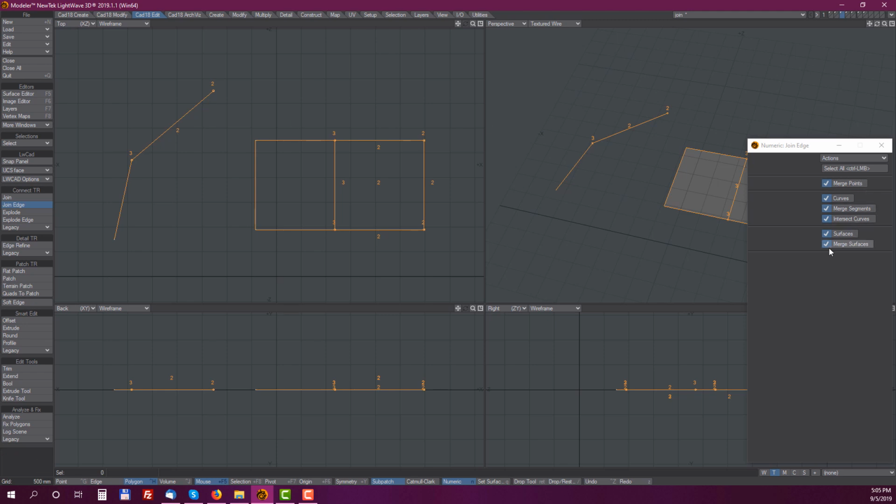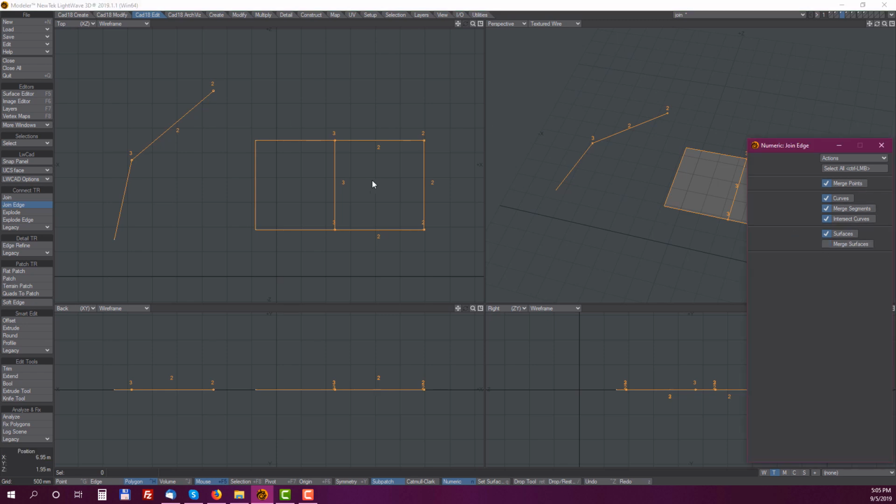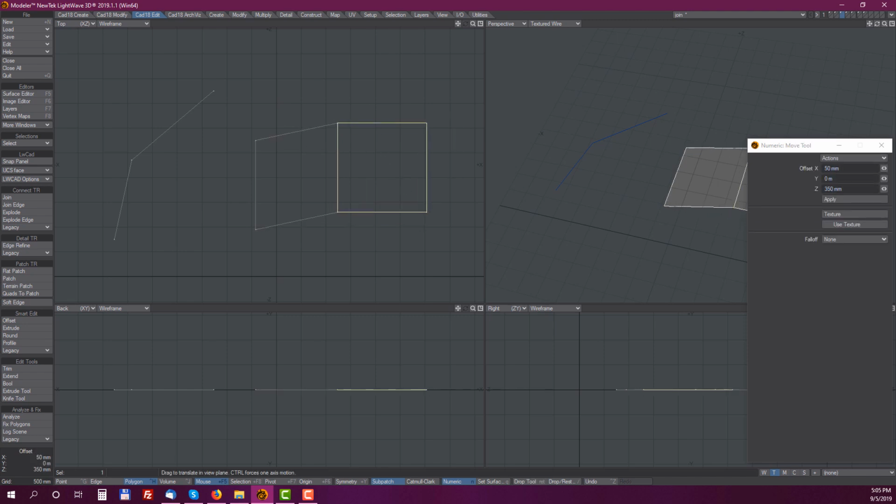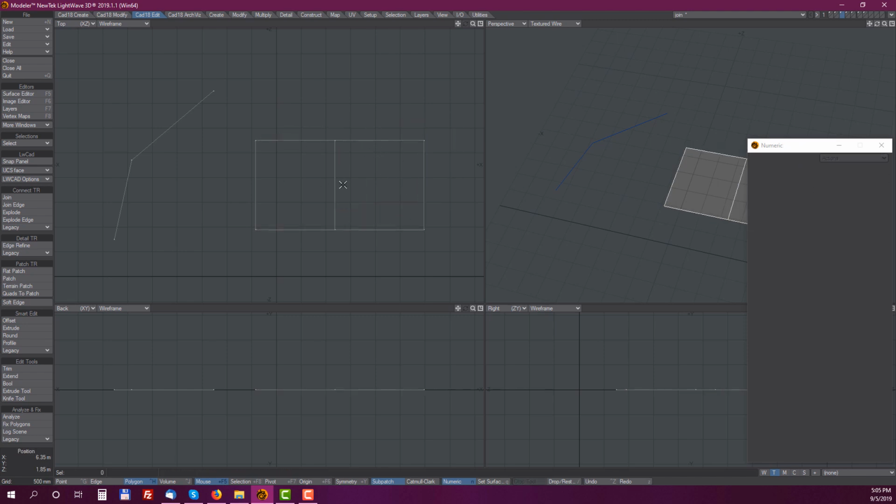merged. If I disable merging, let's say, polygons, you can see these polygons are now not merged. Or if I disable segment, you can disable merging segments. I will leave all options enabled, and the result will be only 2 polygons here, both connected, so that extra polygon was removed, and same for the curve, only a single curve with line segments. So these additional options for merging help to remove unwanted hidden geometry.